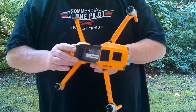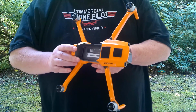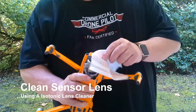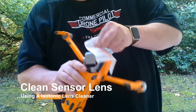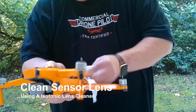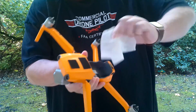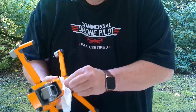And once you confirm that, the only other thing that you can do is to clean them. So all I use is a simple lens cleaner, and I just go over each sensor and make sure that they're clean, that there's no dust or smudges or anything else on them that might interfere with them picking up the proximity of an object.